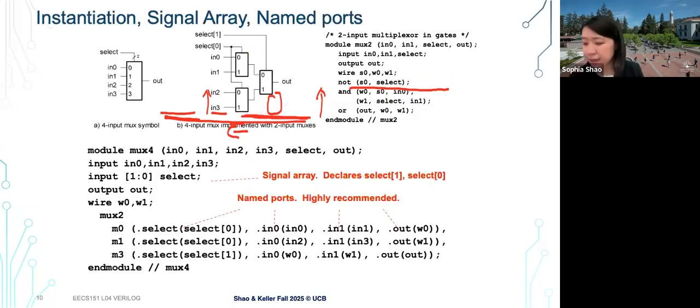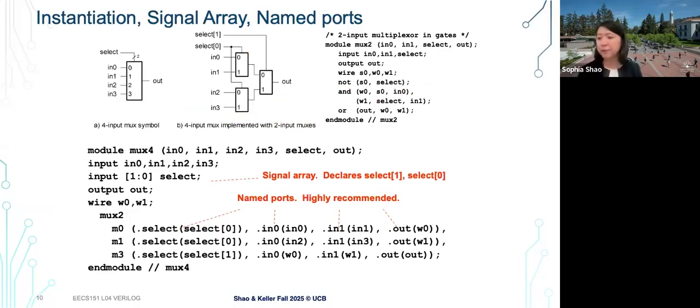So with that, there are some powerful components in Verilog where you can start from a basic block and build more complex things. Let's say, for example, we have a basic module called a 2-input mux, Mux2, with specific input and output signals, and we build up our mux structurally using different basic building blocks.